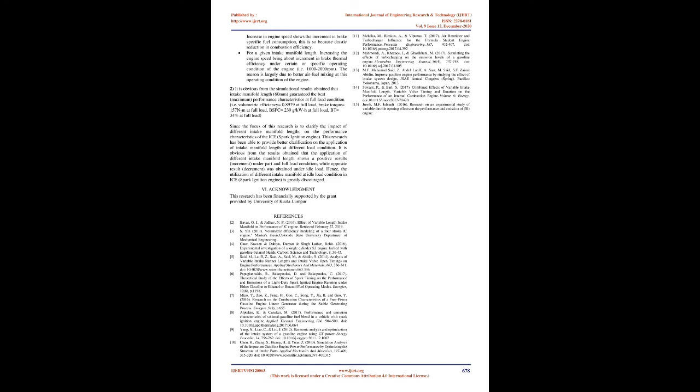For a given intake manifold length, increasing the engine speed brings about an increment in brake thermal efficiency under certain or specific operating conditions of the engine, i.e. 1000-2000 rpm. The reason is largely due to better air-fuel mixing at this operating condition of the engine.